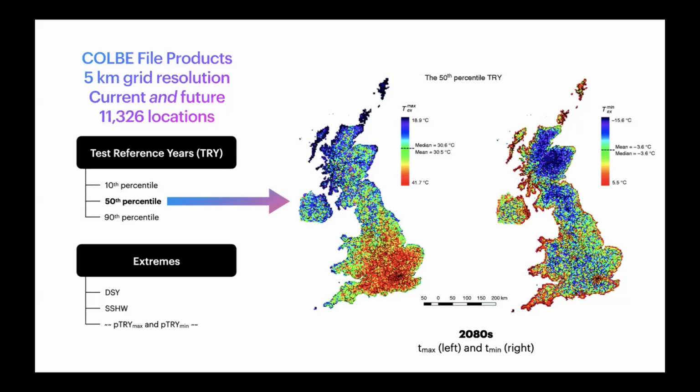And this was a sort of reverse engineered process where we actually don't start with external conditions. We start with bad internal conditions and work out what weather would have caused those bad internal conditions. So essentially, we have a thermal model of a building, and then that is put through a stressing procedure, and we work out what the heat wave would look like. So it puts the focus on indoor conditions rather than outdoor conditions, which is what most of us care about.